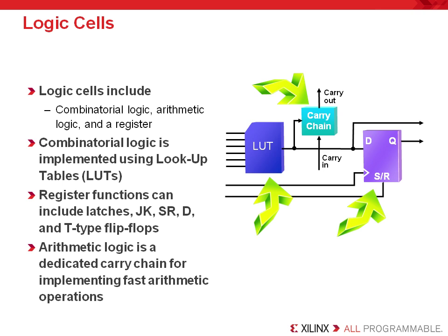Each Virtex 5 CLB has 2 slices. Each slice has 4 LUTs and 4 flip-flops. Basically, this diagram is replicated 4 times to make a single slice. That means that each Virtex 5 CLB has 8 slices. Now, this is not very important. It just makes comparison of devices and device families a little easier if you speak our language.